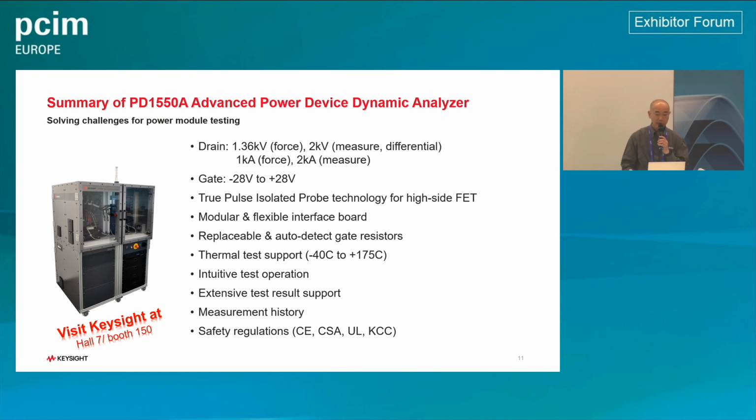All right, so let me summarize what I talked about today regarding PD1550. We believe we can solve most of the challenges you face in characterizing the power module. We have a sufficient voltage range and current range. And we developed the true pulse isolated probe technology for high-side FET testing.